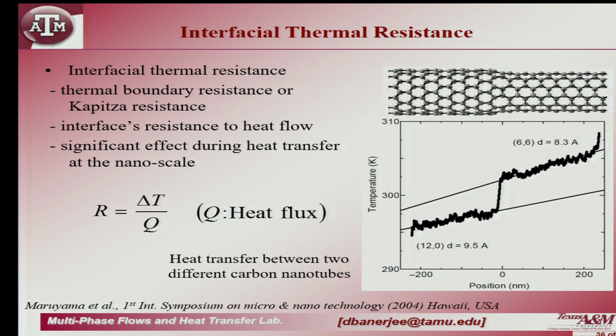So, one good way to understand is it is not contact resistance. Okay. Contact resistance is something different. Okay. So, consider there is a carbon nanotube which has a crystal structure where there are, let us say 12 of these carbon nanotubes around one cylinder. Okay. Now, I go to another cylinder where there are 10 of these carbon nanotubes. So, I am going from a higher diameter tube to a lower diameter tube. It is the same material. Okay. But because this has a higher diameter, its radial frequency, breathing frequency is different, and this one has a different radial frequency, natural frequency, because the diameter is smaller.